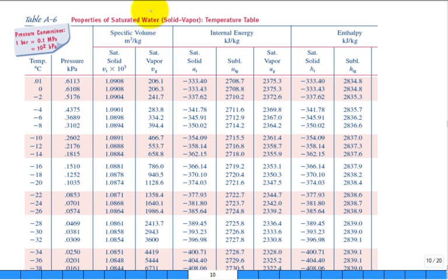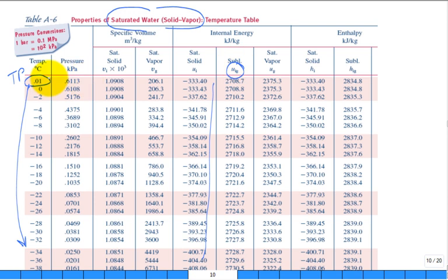And then the solid vapor mixture of water is saturated water. And a couple things to notice. What is the starting point? The highest temperature, triple point, and then you go low, low, low, cold, cold, cold. And take a look at the values of these u's. They're low. And so they're negative, okay? So it's that negative energy. What was our reference point? It wasn't u_g at the triple point. It wasn't u of ice at the triple point. It was u_f was set to be 0 at the triple point for water. Okay, that's why it's so negative.